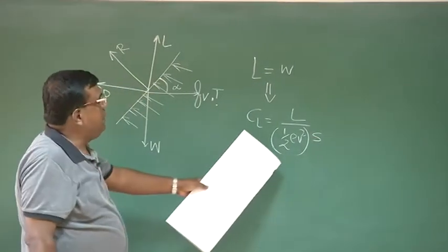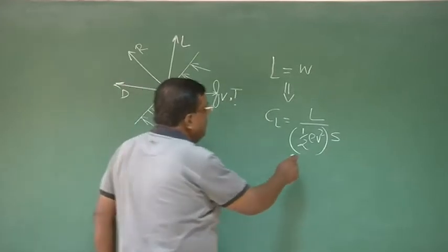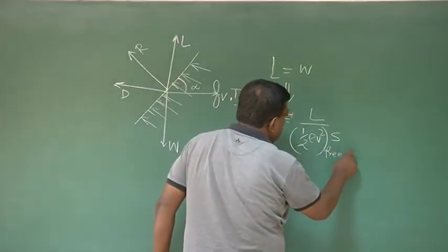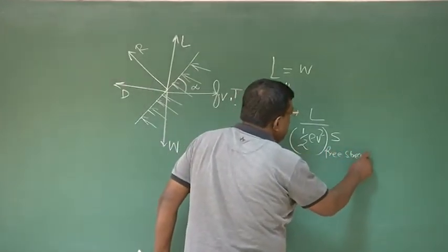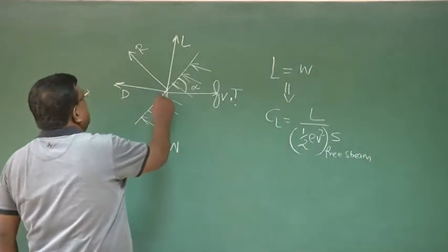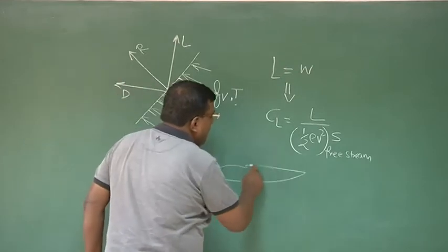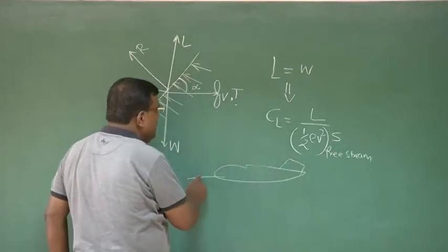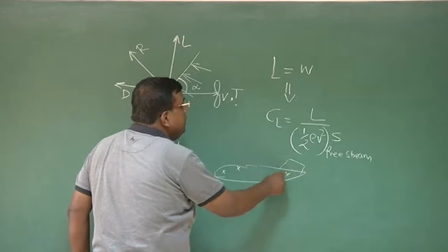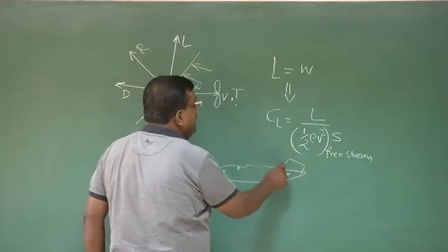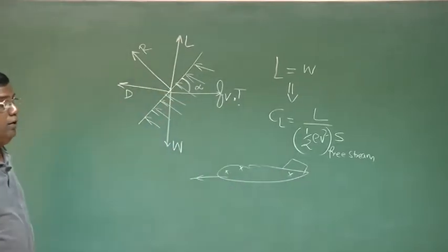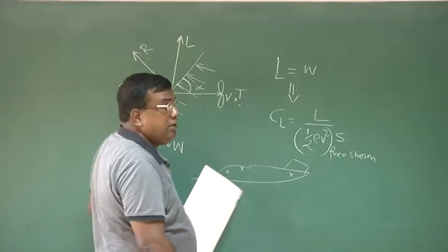And when you say dynamic pressure, we talked about free stream dynamic pressure, because we realized that the velocity at different points will be different. If it is an aircraft moving like this, velocity here, velocity here, or the dynamic pressure here, here, here, all will be different. So when I non-dimensionalize this, which dynamic pressure do I take?